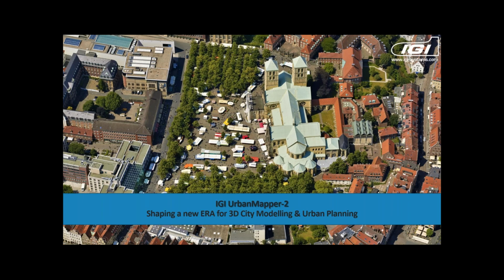It's a very special sensor. We call it a special mission sensor with a 150 millimeter lens, so it can be operated from high flight altitude. It is a professional camera, which means it's delivering photogrammetry grade oblique and nadir imagery. You can also enable the collection of just nadir frame, and you have the largest footprint for the nadir with 450 megapixels. It's a very fast camera.